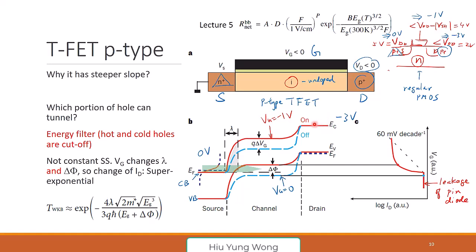So now, the current here, you're just increasing this. I still try to push electron from here. Still, I don't have much electron, correct? Same for hole. Still, I don't have much hole. So no matter how you put this one up and down, my current is very similar because the drain and source voltage is the same. Do you agree? Everyone agree what I say now? It's just a diode, correct? Yes, Professor. Thank you.